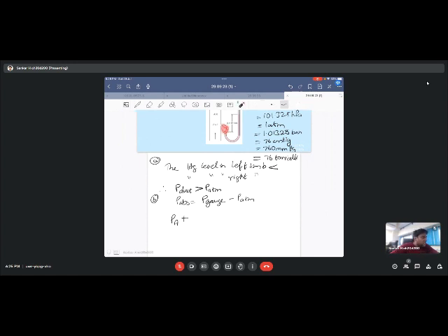Now, assume that the air in here does not contribute to a pressure difference over here. If it's like some other oil or something, we have to consider this height as well. There are questions that I'll come to afterwards. Then this and this point are in equilibrium. That means that the pressure over here and the pressure over here are the same. So we'll be calculating a pressure from here to here. We'll be adding that. And at the same time, we'll be subtracting the pressure that is from here to here.